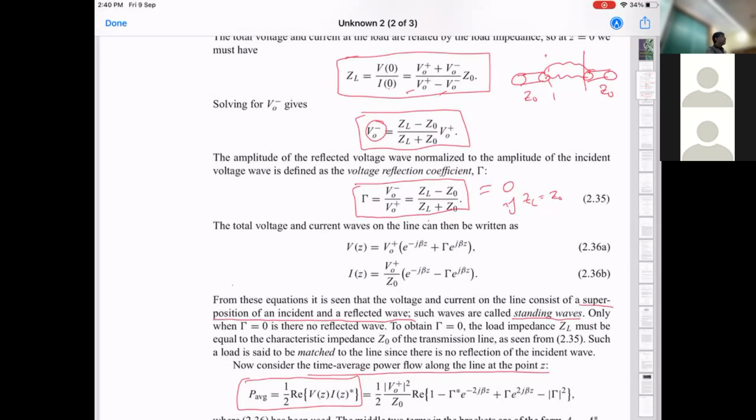It's one-dimensional, and we're just talking about voltages and currents and not about electric and magnetic fields, though they are all interchangeable, right? Because between two plates, if I have a voltage difference, I have an electric field between them. And if there's current flowing through the wire, then I have magnetic fields. This connection between the electromagnetic picture and the one-dimensional transmission line picture, we have not discussed in detail yet. We will do that in one of the upcoming classes so that aspect is clear.